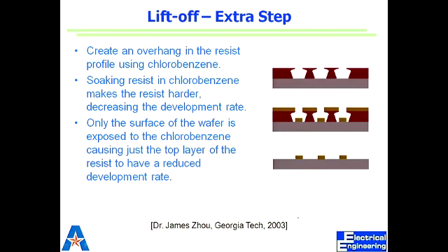Can you use lift-off for something other than metal? Yeah, you can use lift-off for anything. It depends on if you want to make a line or a feature, then you can do lift-off for almost anything. But why do we usually prefer it for metal? Because if you want to etch metal, you'll have to use very rigorous recipes.